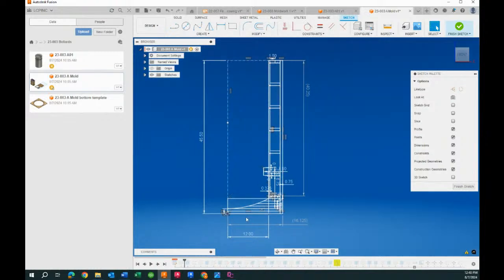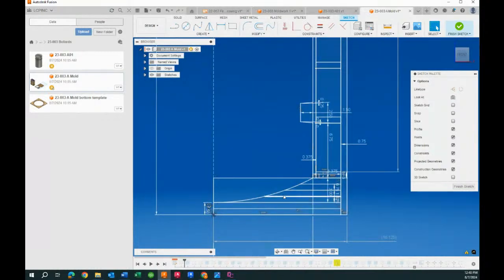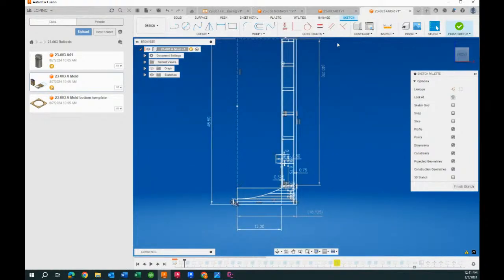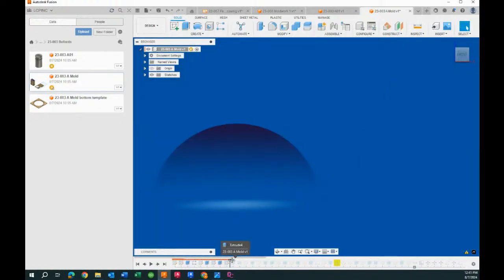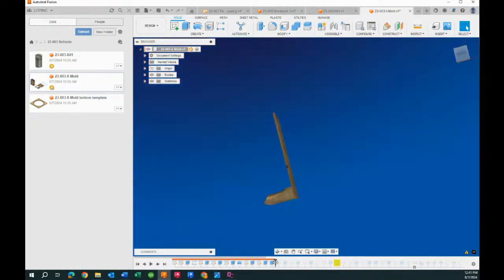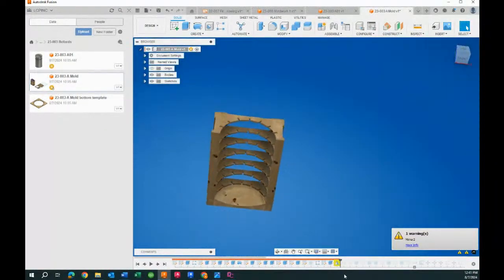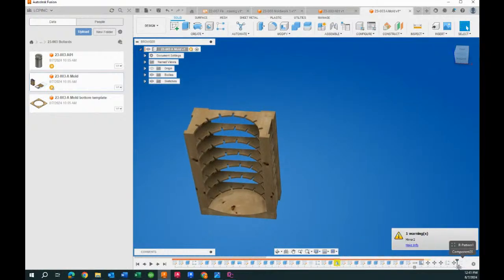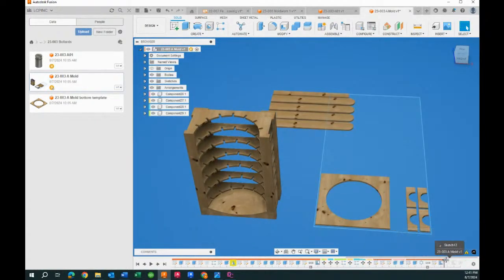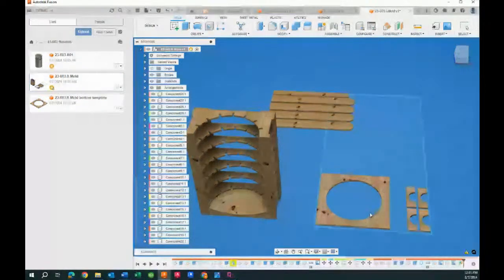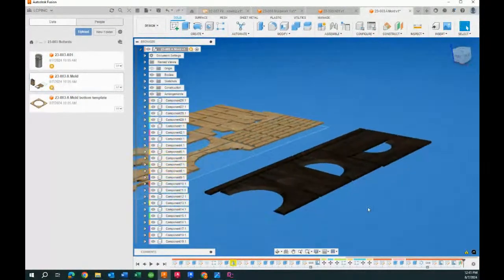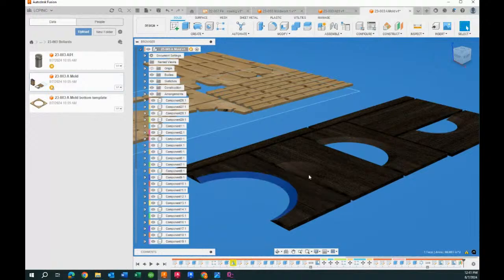But in this case, on this bollard, we knew we were going to have a radius-shaped face. Because we didn't have a large bit, we knew we were limited to 3/4 of an inch. So we ended up creating a series of bodies that we would then come back in and create the form, basically extruding out all the individual parts and pieces, and in the end laid it out flat to cut out these individual elements on a sheet of plywood.